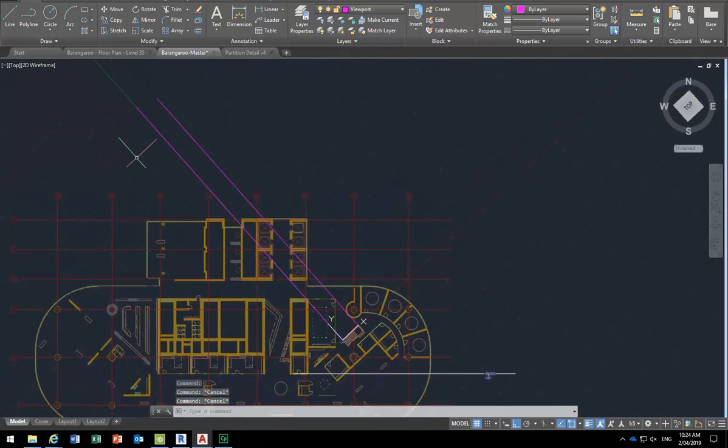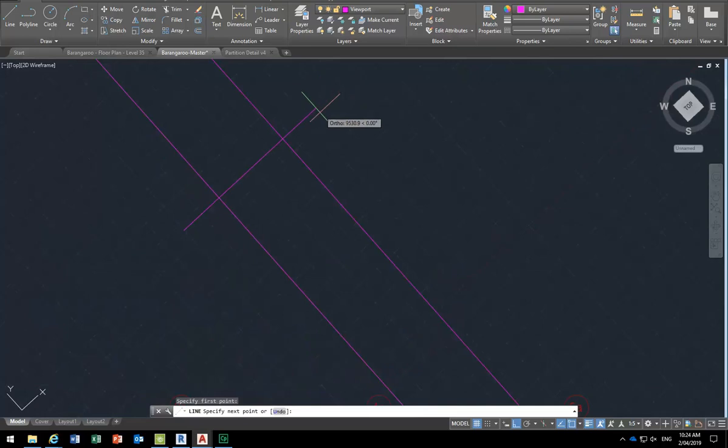If you get the one from Revit, you'd have to then rotate it to follow this angle, but I'd highly recommend that you keep it as an Xref. So insert it as an Xref, and that'll be your base underneath what you draw over the top in this file. And if it's an Xref, you can always update any changes you make from there. And so here we can draw lines. This will be the floor.